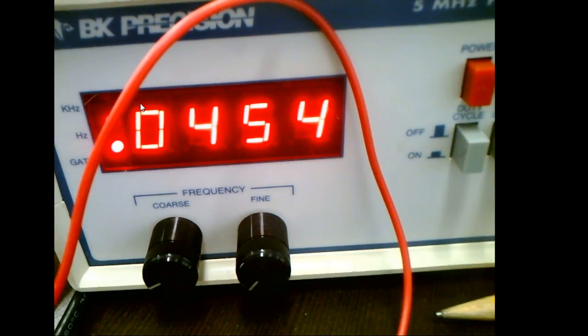So on the test, they ask you to find the frequency, but they give you the time. They give you the scope display. They tell you what the controls are set on. They tell you what the voltage per division is set on and the time per division. You measure the time for one cycle, and then hit the reciprocal, and that'll give you the frequency. There's nothing else. I just have to review.